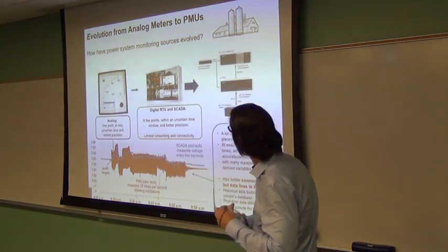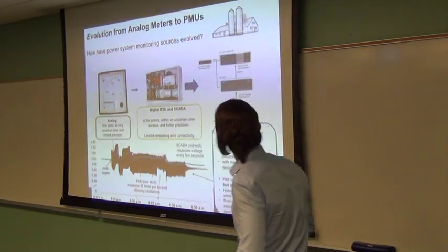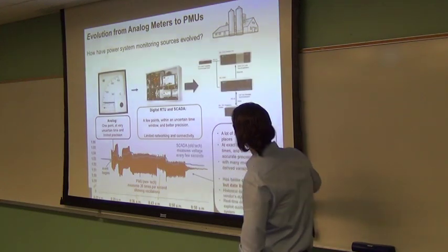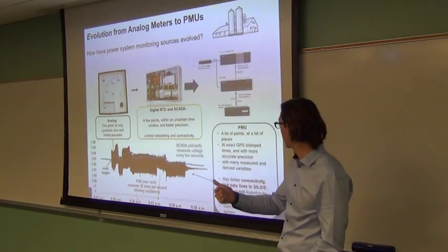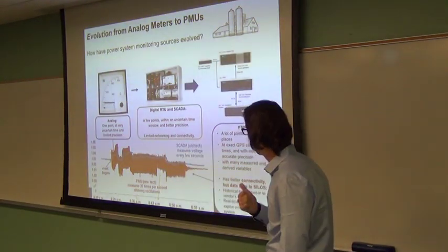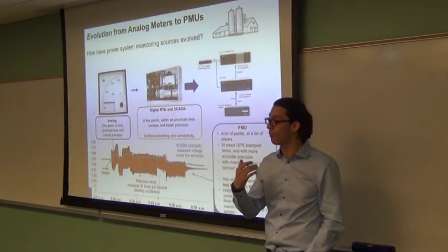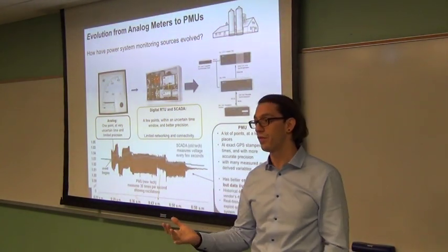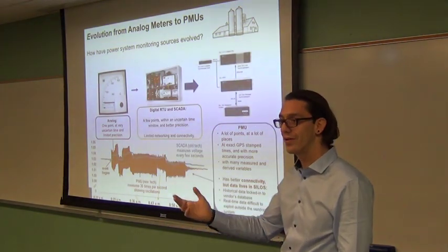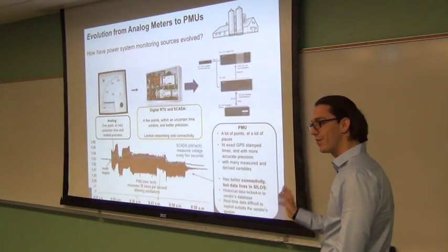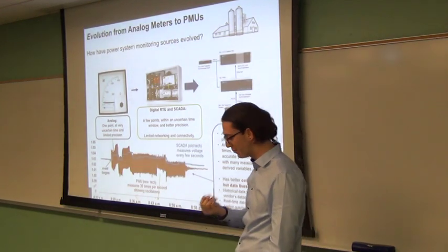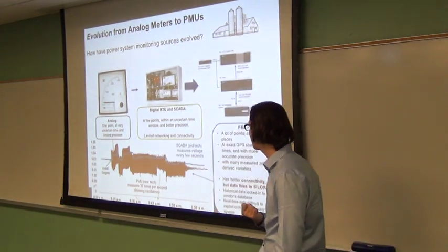And now we have PMUs, all right, or synchrophasor technology. So you get a lot of points. You get exact GPS time with much more precision. You measure a lot of variables. So now you measure phasors. You don't measure power; the power is a secondary result. You measure the innate quantities.